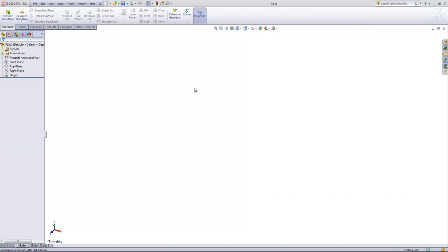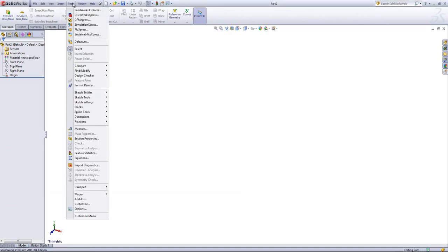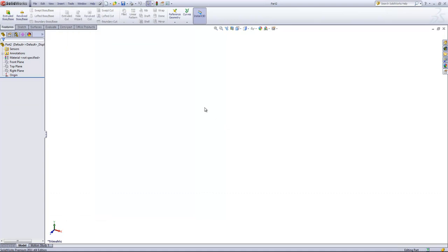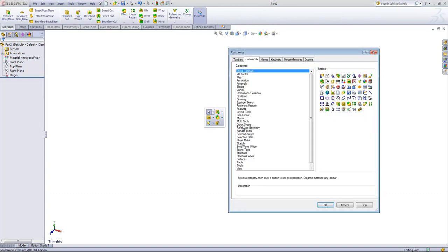Depending on what kind of part, assembly, or drawing you're creating in SolidWorks, you'll be using different tools to get the job done. These tools, as stated before, can be found in the Command Manager, as well as the pull-down Tools menu. But there are also several more convenient shortcuts. The first is pressing the button S, which opens up the Shortcuts bar. This comes preset with several features, but this can also be customized by right-clicking and choosing Customize.